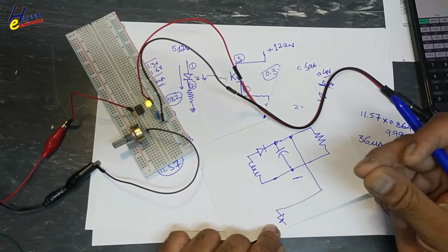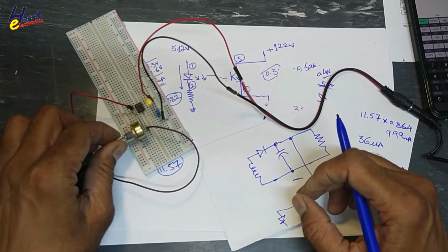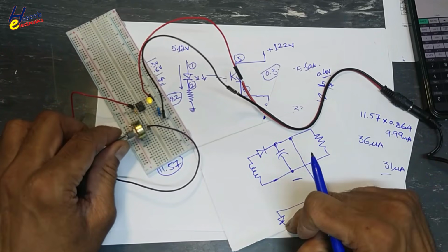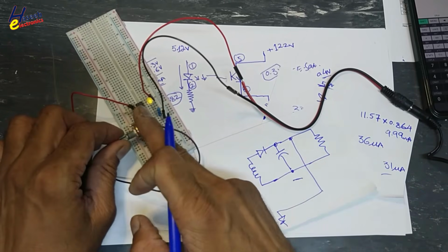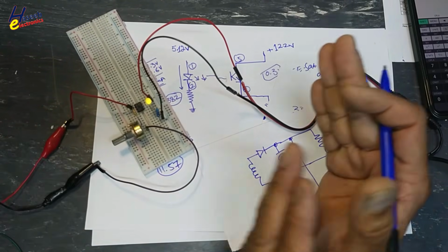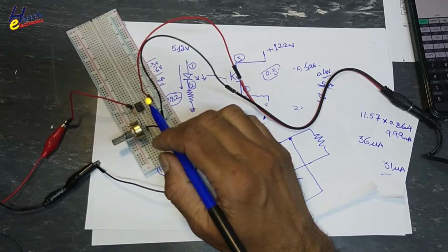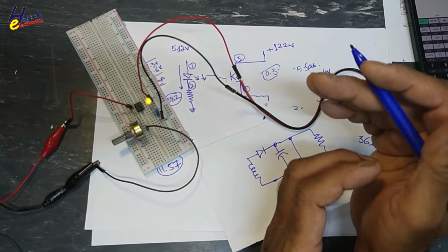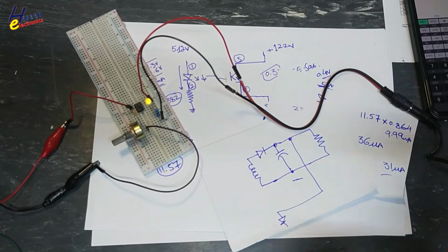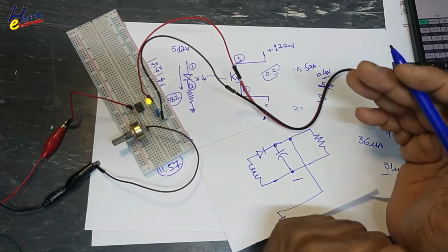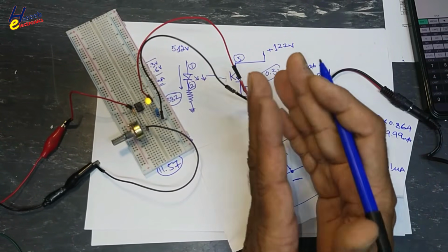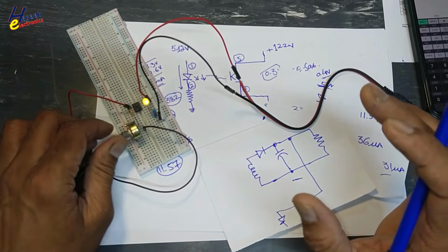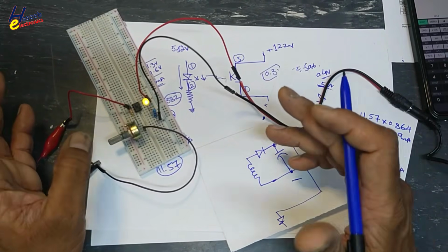Optocoupler current will change. How? With this ratio. When this current will change, the same ratio is being transferred in the secondary side. With this changing light, with this changing current, PWM controller will understand what is the change, what is the load side in the output. So that will control its duty cycle to control the output voltage. So this is a role of optocoupler in any power supply.